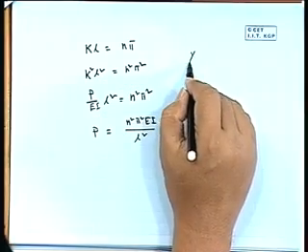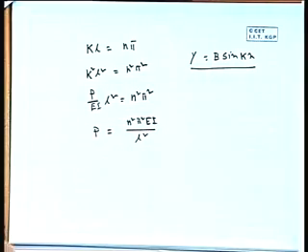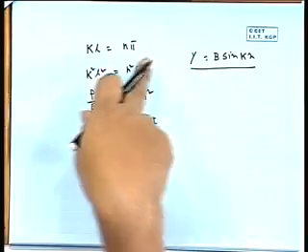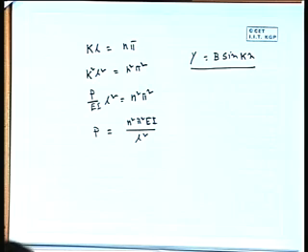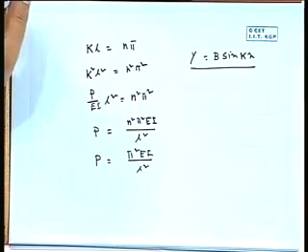Right. So we got one deflected shape, y equal to b sin kx, and KL for that case, when b is not equal to 0, is KL equal to n pi. So from there we are getting P equal to n square pi square EI by L square. Now if n equal to 0, what will be the value of the load? 0. 0 means there is no load, it will be straight. But if n equal to 1, P will be pi square EI by L square, right?